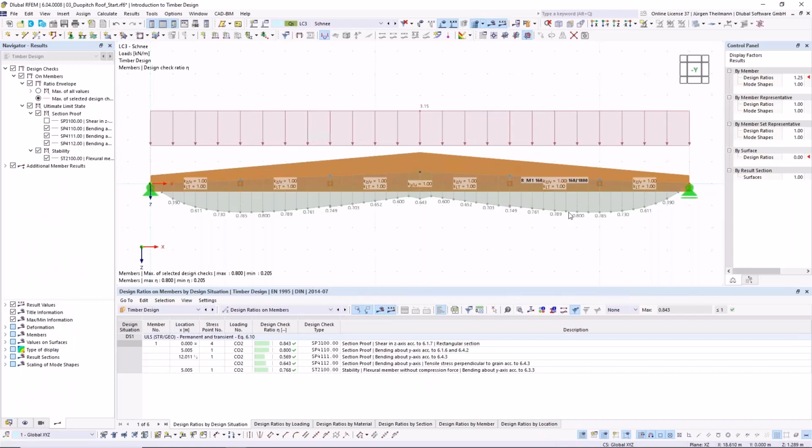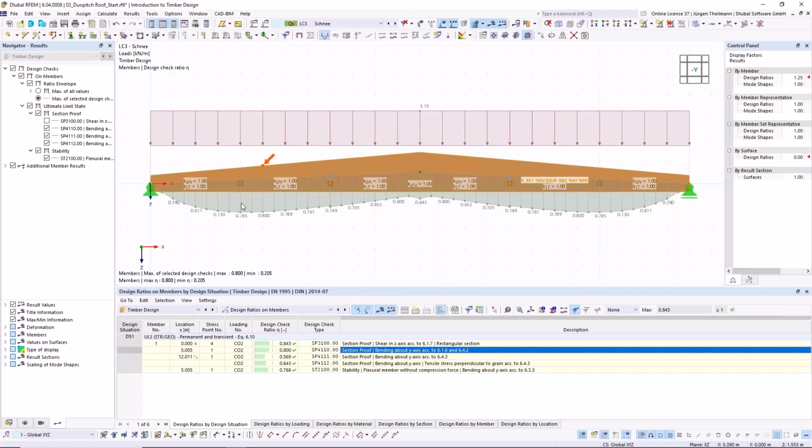And now you can see a very nice looking distribution, and you can identify pretty easily the place of the maximum bending stress. So this is maybe now too fine, but always remember the rule from FE calculation that the mesh has to be as coarse as possible, but still as fine as necessary.